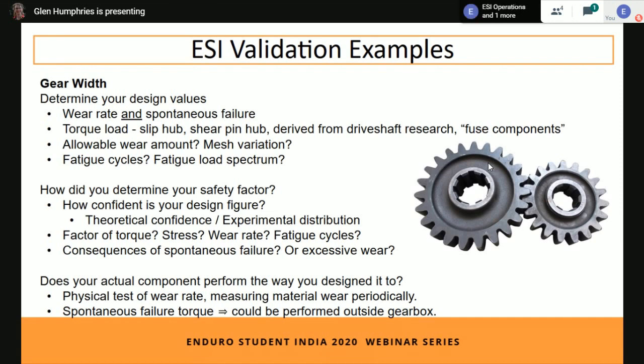But in something like this, where we're having a lot of trouble coming up with a good design value, we don't want to guess, because we're actual engineers and we don't guess these things. It's hard to come up with a value. And so we can resort to other, more wasteful strategies, such as making sure it's stronger than the other component further down the drive line, in terms of the amount of torque that's going through it. Now,